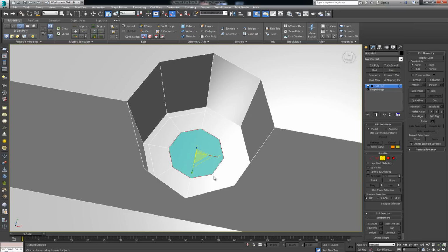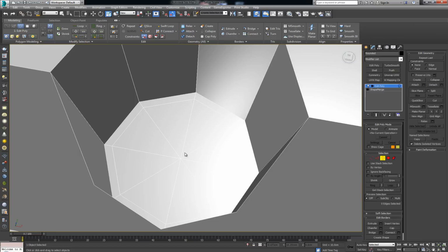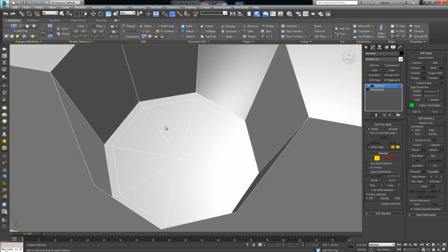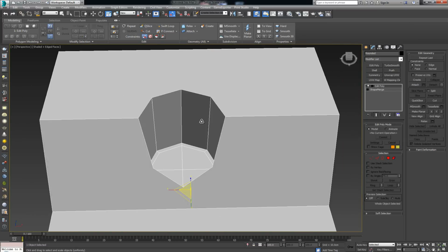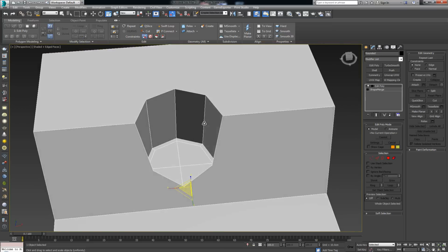So now, since I have this second part, I can simply click on collapse, and this is going to collapse it here. If I want to keep this with quads, I can simply select one, then skip one, select one, skip one, Control Backspace, and here we go. Now we have nice quads in the middle part over here. All right, so there we go. Nice little cut in.